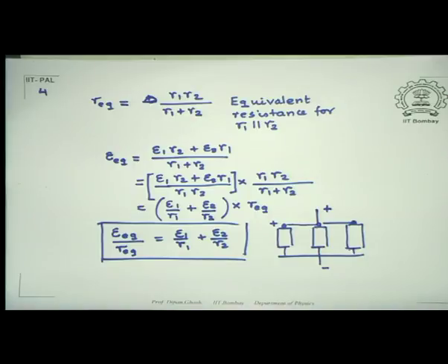So why parallel combination? One of the things that you notice is this, the voltage that I get is the same because of the parallel combination, but it provides a higher capacity rating for the same voltage. So for instance, if you added two 1.2 volts batteries in parallel, and let us suppose each one of them has a rating of 1000 milliamp hours, because that's the typical small batteries, they don't consume a lot.